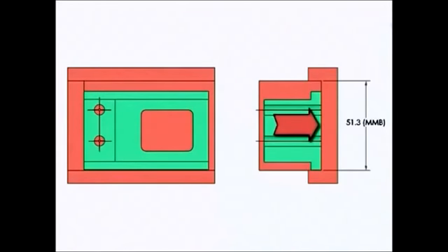The part has to stay against datum feature A, which is this surface, so there's no shift in that direction, and it has to stay against datum feature C, so no shift left-right. The only shift allowed is up-down if the part is made smaller than the maximum material boundary of datum feature B.